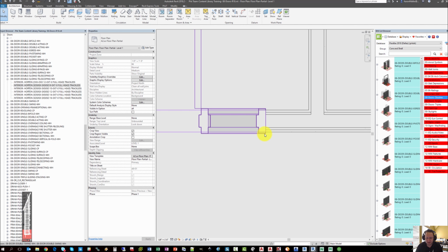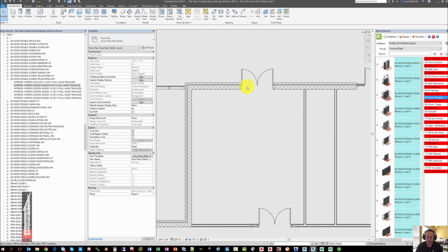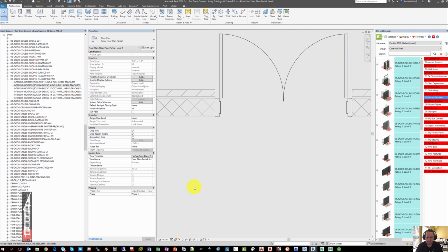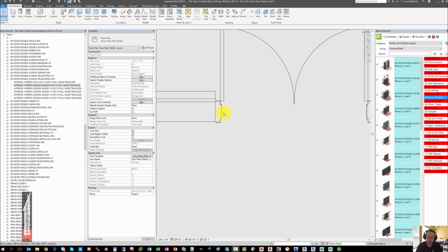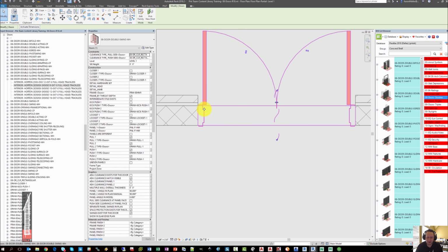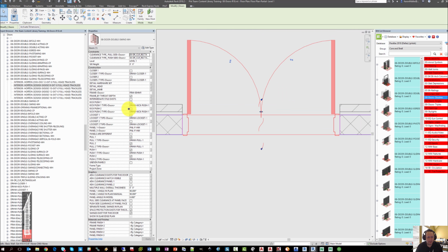However, it's not always optimal to have the door frame automatically changing with the walls. Exterior walls are a great example. If you have exterior cavity walls or walls that have large framing members or masonry, you might not want the frame to actually cover the entire wall the way normal doors do in Revit. So you have a box that is called frame by throat depth. Unchecking that parameter does what we call breaking the door off of the wall itself. The wall may appear to jump when you uncheck this box.